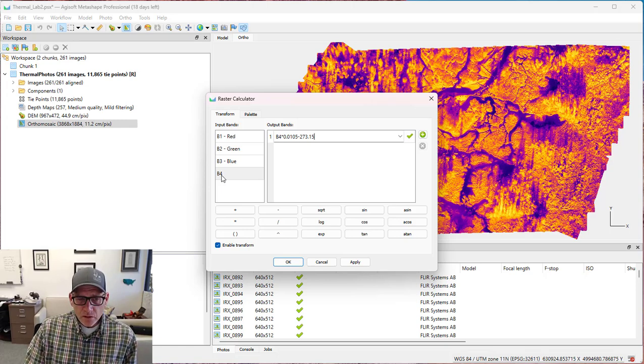The published equation for this would be to multiply the pixel values times 0.01. We actually had temperature loggers along this stream, and when we did this, we found we got closer matches to our in-stream temperature loggers if we modified this equation a little bit. So that's how I got the 0.0105 value here. And again, that's just a rough ballpark. We could probably do a better job by doing a regression between the two, or plotting those out. But this will serve for right now.